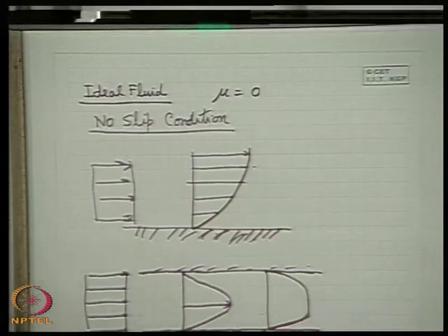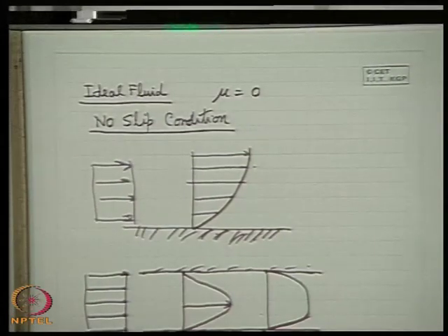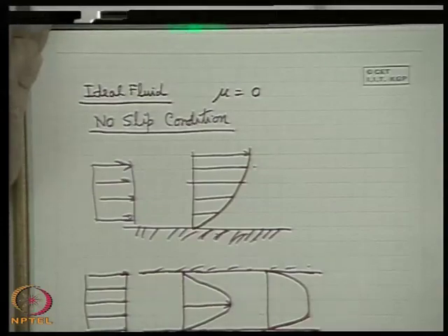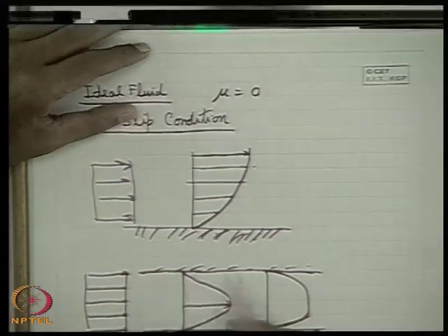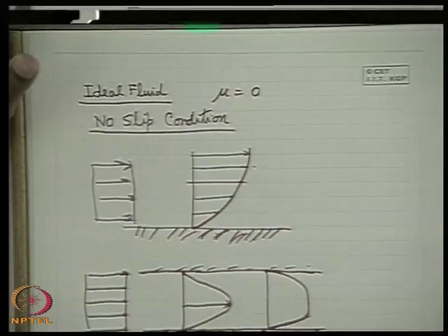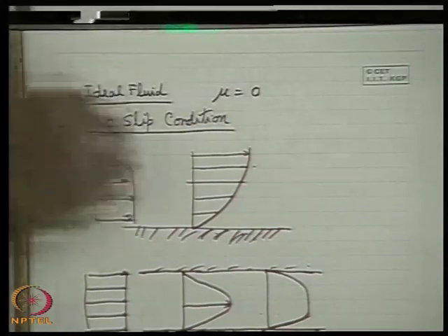This is the case when the flow is turbulent. This is the turbulent flow condition, which will be taught afterwards. This is the laminar flow condition. So whatever may be the velocity variation, the difference in their trend for laminar flow or turbulent flow depends upon the flow velocity. When the flow velocity is very high, the flow becomes turbulent. In both situations, the flow velocity is 0 at the solid surface. This is precisely the no slip condition of fluid.